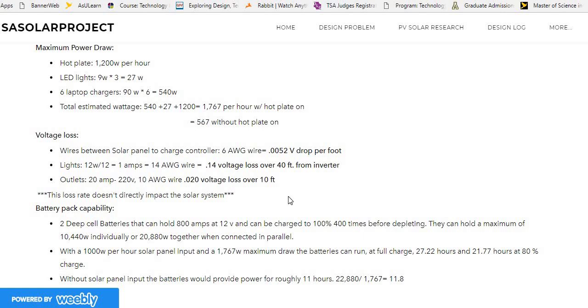What's important to think about here is that in theory the school would only be cooking probably 2 meals a day, and that would only take about an hour at a time. So this total load here would only be used about 2 hours a day, whereas this load would be used basically the other 6 hours of the day that school would be in session.